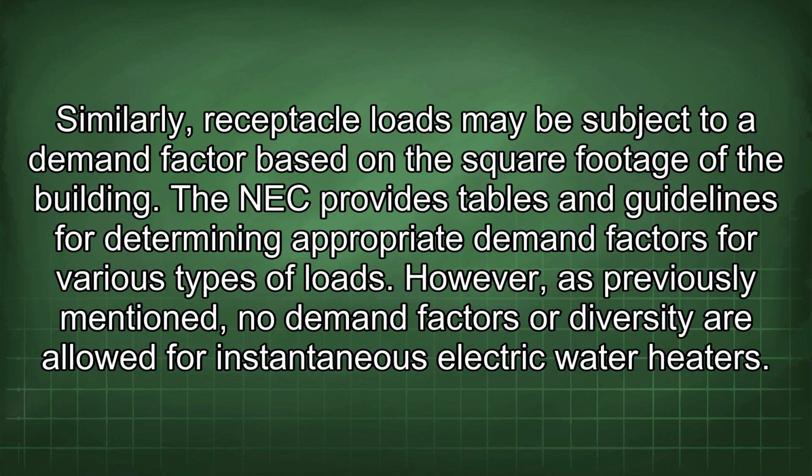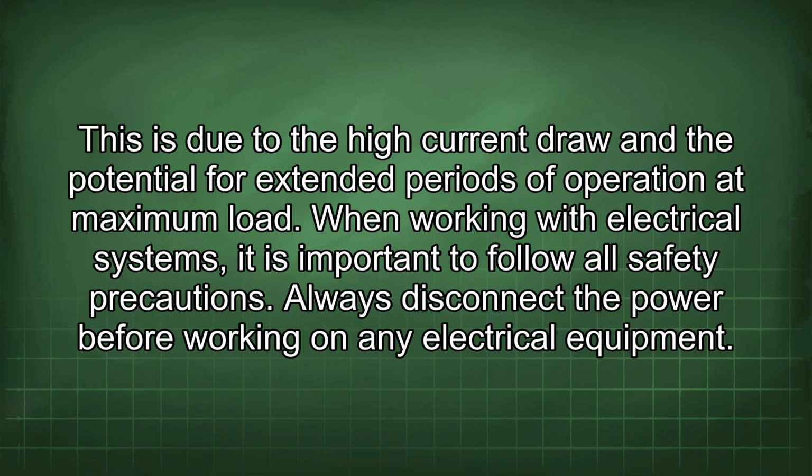Similarly, receptacle loads may be subject to a demand factor based on the square footage of the building. The NEC provides tables and guidelines for determining appropriate demand factors for various types of loads. However, as previously mentioned, no demand factors or diversity are allowed for instantaneous electric water heaters. This is due to the high current draw and the potential for extended periods of operation at maximum load.